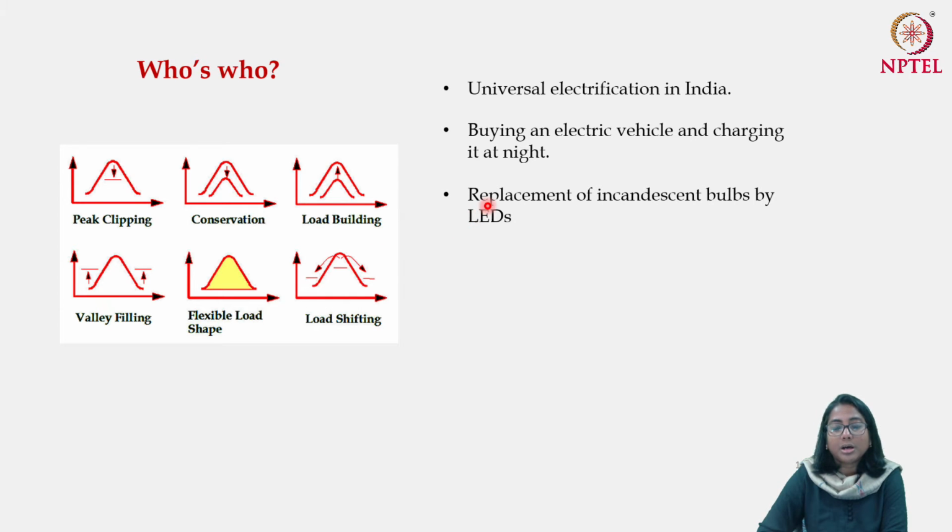However, if you think about a particular household or the residential sector, probably the demand for lighting service comes during the evening, late evening, night, and so on. So if that period is the peak demand period for the residential consumer, then replacement of incandescent bulbs by LED will actually lead to peak clipping. So during the peak period, your demand is coming down. Nothing happens to the rest of the time where you actually do not have any requirement for lighting services. So there can be multiple options as well.